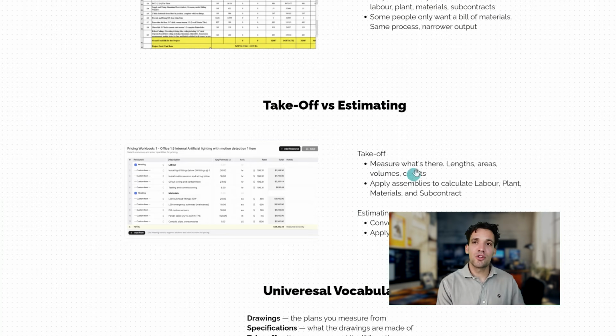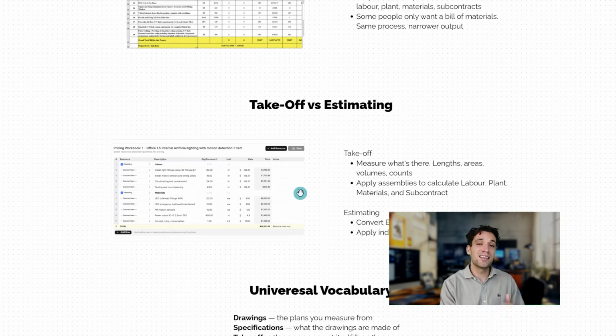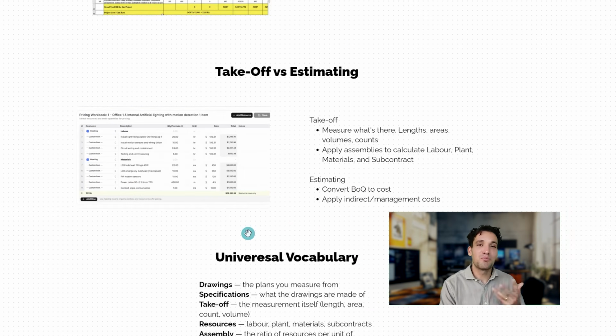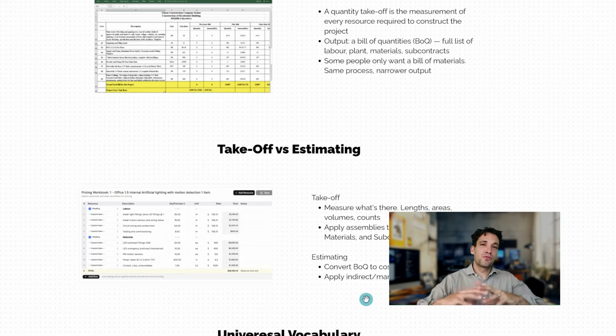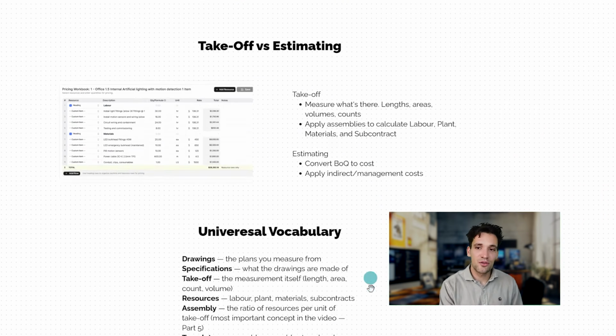The other sort of framework you could use is the takeoff is, I'm going to use the term relatively, relatively objective in terms of how you actually build out the bill of quantities, because at the end of the day, you're measuring stuff. There is some subjectivity when we're talking about applying production rates to calculate labor, but I'll talk about all this later on. But then the estimate becomes much more subjective. So takeoff is really assembling the raw data. An estimate is applying costing and the business strategy to actually win the work. It's much more subjective.